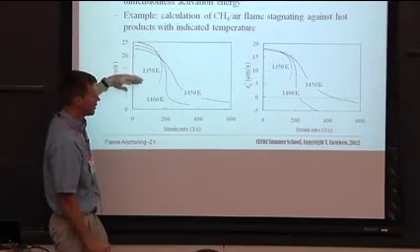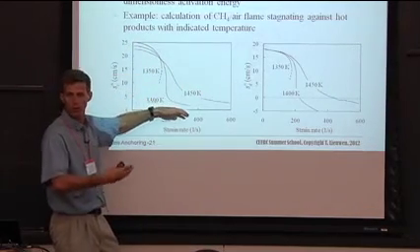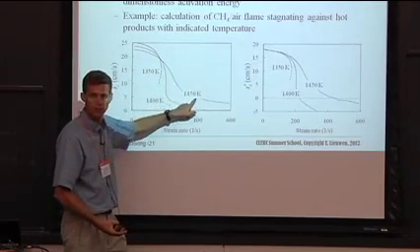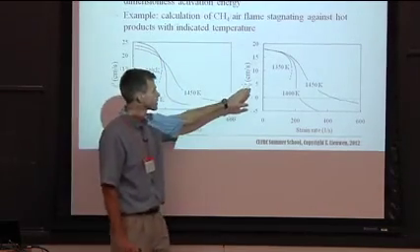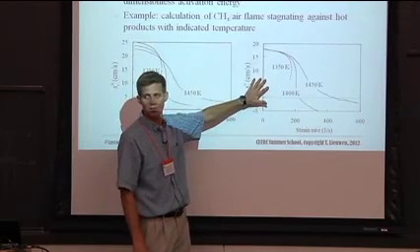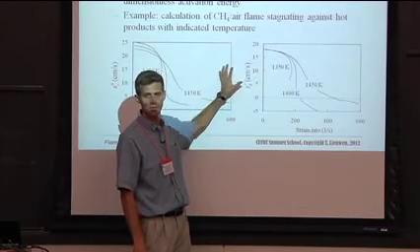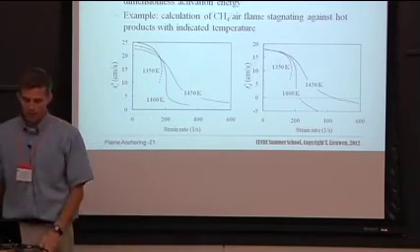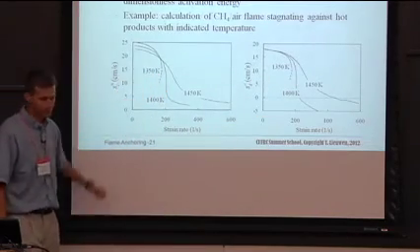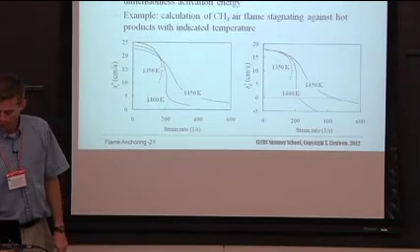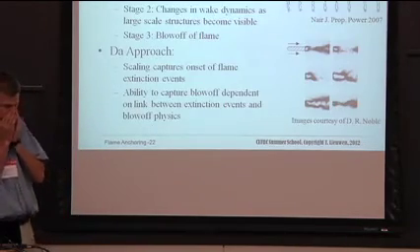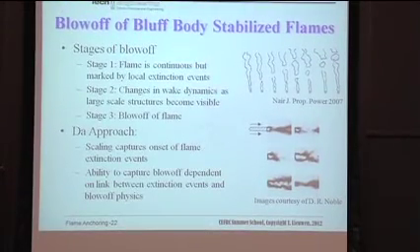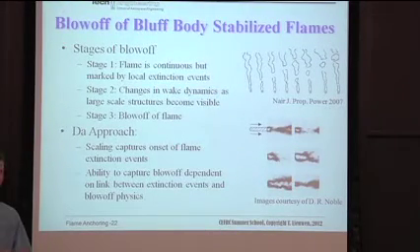So what that means is I can stretch the flame more and more and more, and it just kind of hangs on. I just get less and less combustion. I'm also plotting the displacement speed here. How many of you are familiar with the difference between consumption and displacement speed? So never mind. Just worry about the consumption speed curve. So that happens. And so what that means is that as long as you've got product recirculating, that flame's just not going to extinguish in the shear layer.